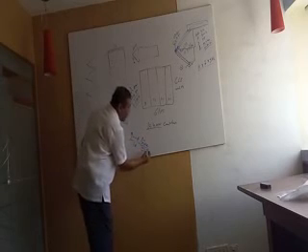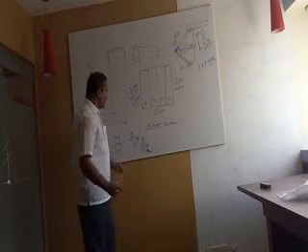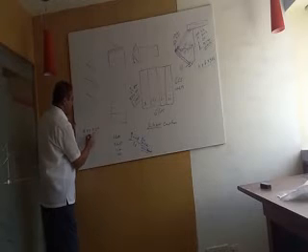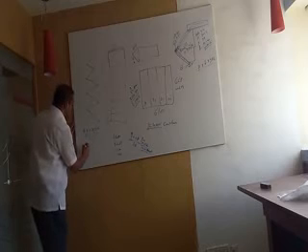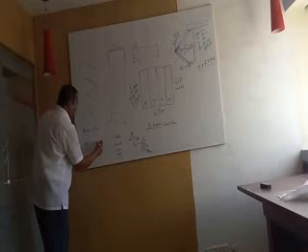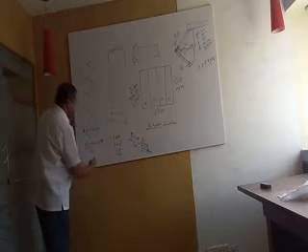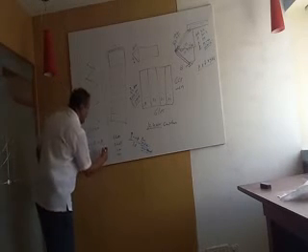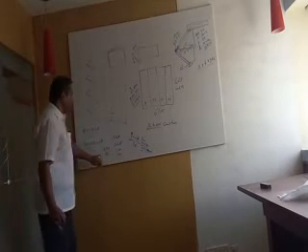Amps into volts into service factor divided by 1000 gives you the kilowatts consumed. So 1440 amps into 440 volts into service factor 1.7 by 1000 gives 1077 kilowatts. This is the energy consumed for pumping.